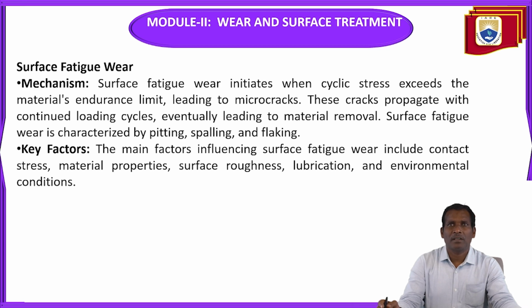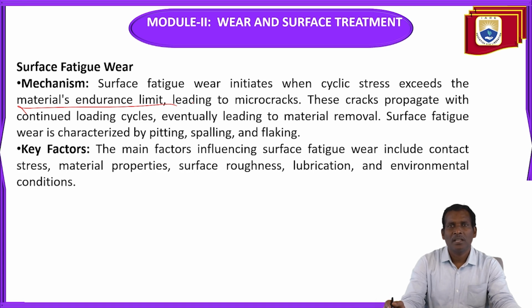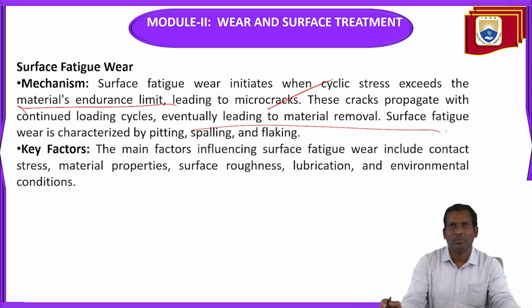Surface fatigue wear initiates when cyclic stress exceeds the material's endurance limit, leading to microcracks. These cracks propagate with continued loading cycles, eventually leading to material removal. Surface fatigue wear is characterized by pitting, spalling, and flaking.